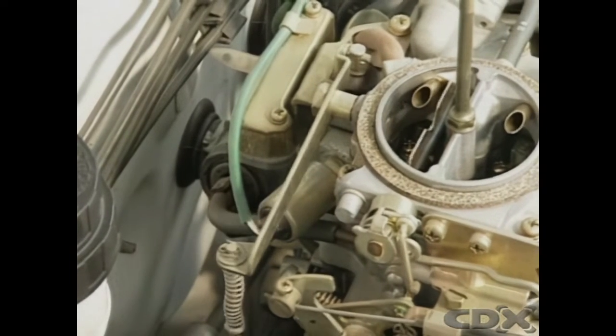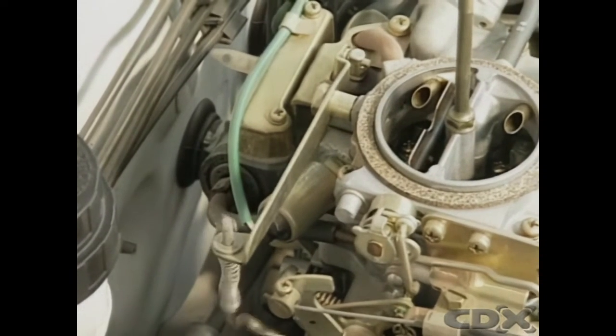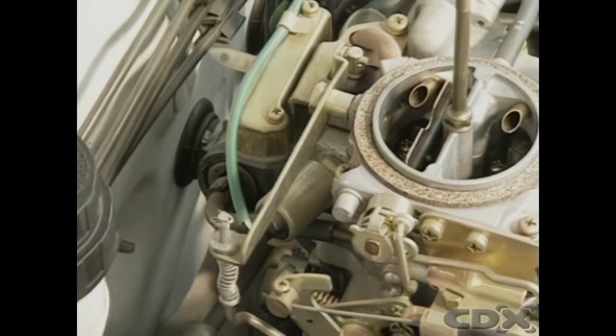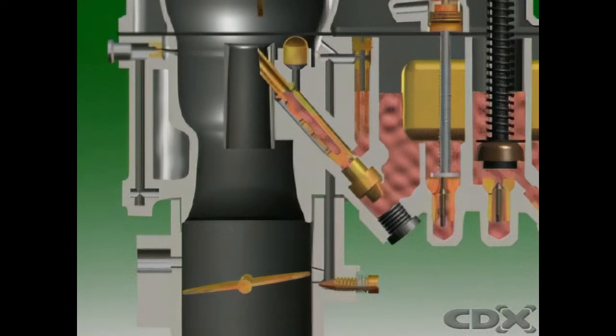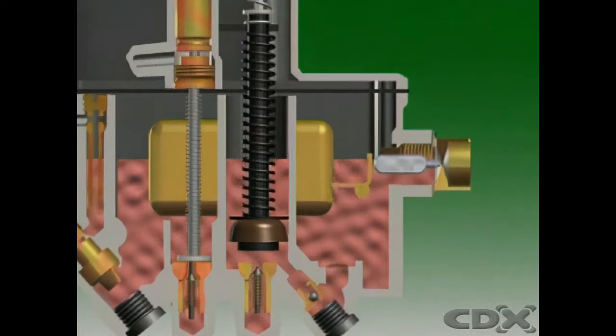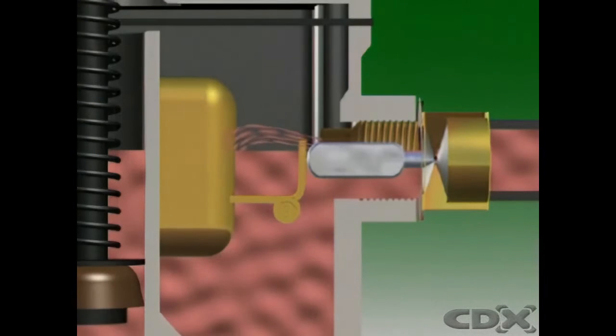The carburetor supplies the engine with the correct mixture to suit all operating conditions, from idling to high speed. To do this, it has a number of systems. With the engine stopped, the throttle valve is closed, but fuel is still held in the bowl. With the engine running, fuel is held at a set level by the float and a needle valve. Fuel supplied to the engine when it is running is replaced by fuel from the tank.